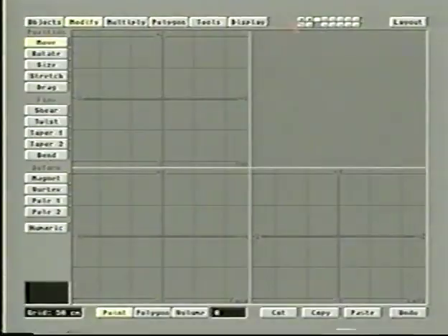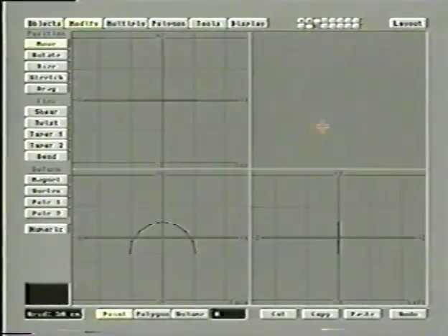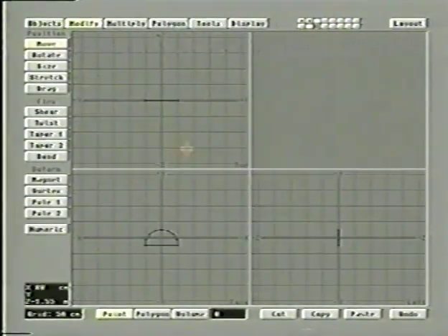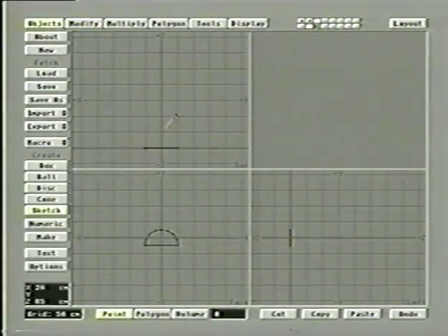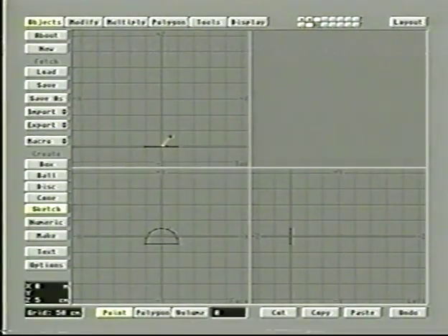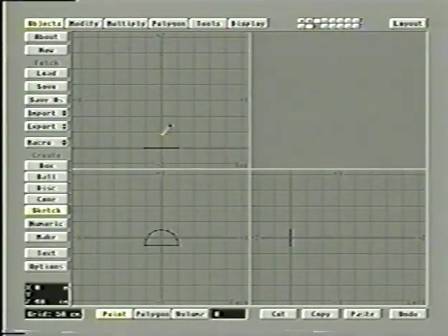With rail extrude, you use 2 different layers, one for the sketch path and one for the object you want to move along that path. So let's make layer 2 visible in the background or inactive layer by clicking on its bottom button. And now from here, if we go to the top view, let's go to sketch and sketch out the path that we want this object to follow. Just click and drag. I'll give it a curve here.